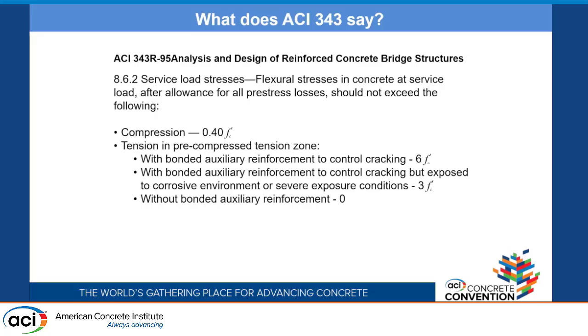So why is this important? I'm trying to keep that crack small or no crack, right? Zero tension means no cracks. So that crack opens up. Our bridges are in very severe environments. Now that's an opportunity for corrosion and deterioration to take over. So the fact that we're seeing that these loads far exceed the design loads and what we're looking for at service limit state is telling me that that bridge is going to deteriorate much quicker than what we expected.